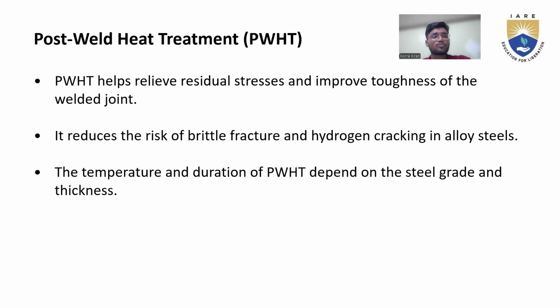Here we can observe post weld heat treatment. Post weld heat treatment helps relieve residual stresses and improve the toughness of the welded joint. PWHT mainly helps improve the toughness of the joint by relieving stresses, and it reduces the risk of brittle fracture and hydrogen cracking in alloy steels. This will happen during PWHT.